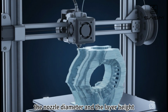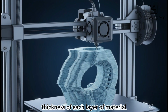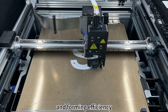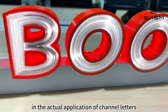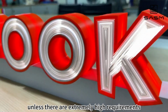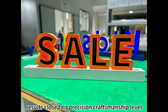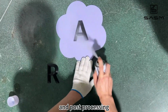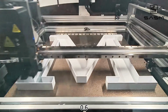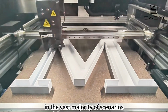The nozzle diameter and the layer height together determine the deposition thickness of each layer of material on the heated bed, thereby directly affecting printing accuracy and forming efficiency. In the actual application of channel letters, unless there are extremely high requirements for surface texture, for example, results close to a precision craftsmanship level, and post-processing such as sanding and spray painting is required, a 0.6 mm nozzle can already meet the needs in the vast majority of scenarios.